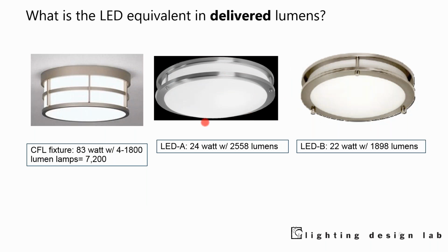So one thing that we see, especially with decorative fixtures, is it's a little hard to determine what your light levels are going to be. And you can't just look at lumens, which is often the only information you have, short of careful photometric analysis. So here we have a fluorescent. Here's our existing fixture, decorative. Maybe you've got a hotel, you've got hundreds of these, thousands running down the corridors, and they use 4 18-watt, 1800 lumen compact fluorescents. So we got 7,200 cumulative lumens.